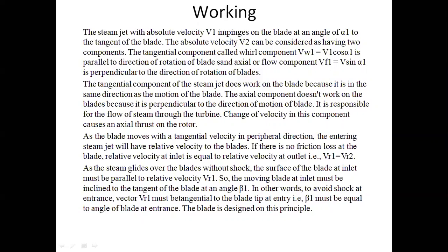In other words, to avoid shock at the entrance, vector VR1 must be tangential to the blade tip at entry. Beta 1 must be equal to the angle of the blade at entrance. The blade is designed on this principle.